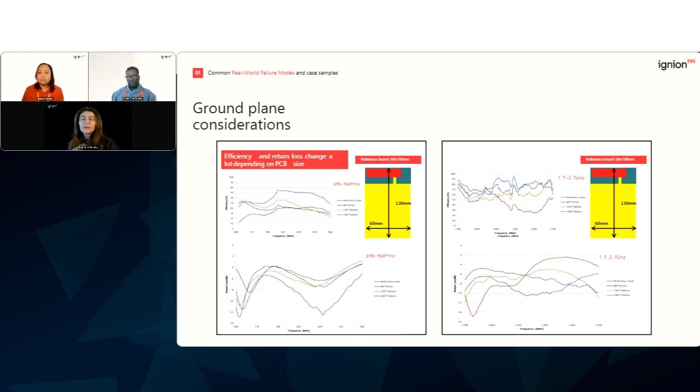If you have smaller, if you have bigger, well, bigger is not so dramatic, but smaller, if you have wider, if you place your antenna in a different place than they placed it in the reference board, that will all show different figures. And what you can do, of course, I understand that you cannot always have this optimal length of the PCB, right? Optimal position. You always need to tune your antenna in your environment. So usually each antenna has some matching network, right? So at least you can work with that. You can tune this antenna on your PCB and maybe even think about that before.